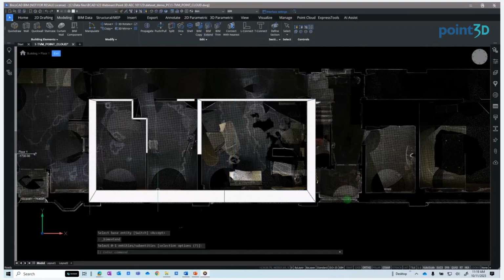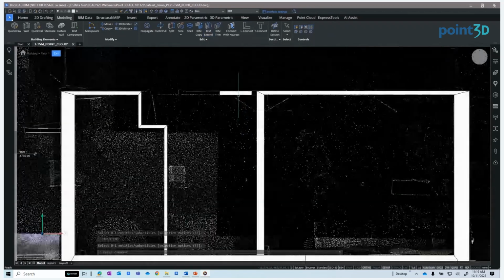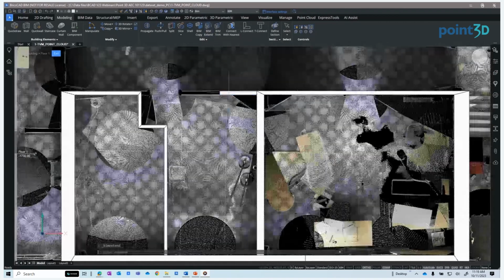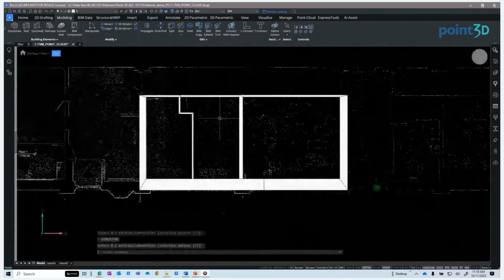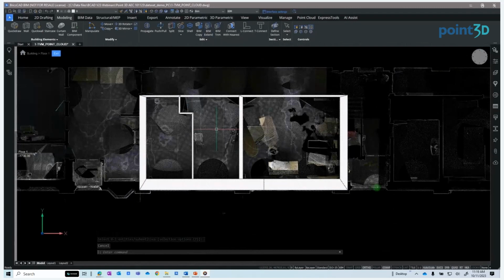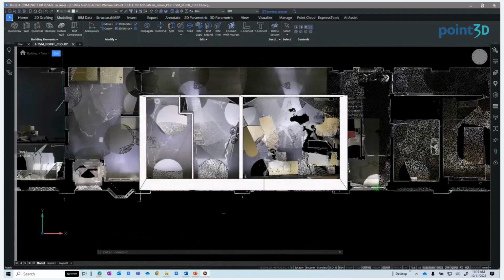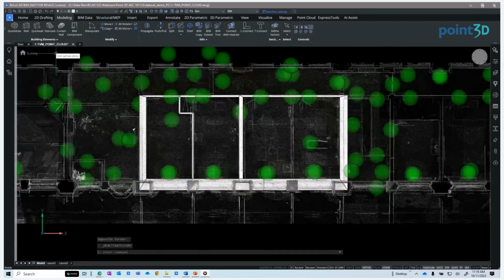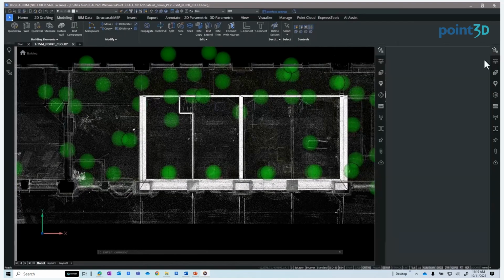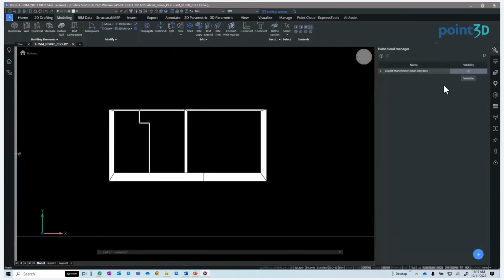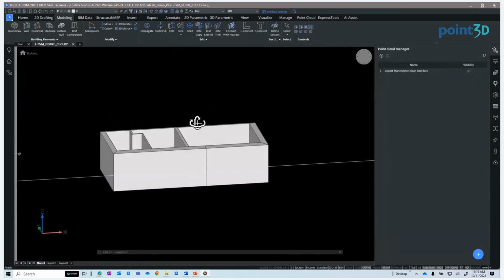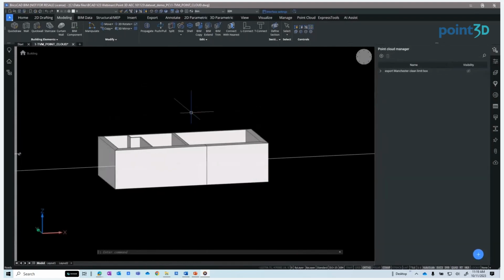Now, BIM Extend detects the nearest wall in the same plane and connects those two. So with the help of these tools, a 3D model of the walls is done. But again, the model isn't perfect. We could probably tweak some of the wall connections, but in a matter of minutes, we've started a model. So let's take a look at the geometry created with the BIM wall tools. And again, even though we're working in top view mode, which is like plan view, this is a full 3D model. Next is to add windows and doors to the model.